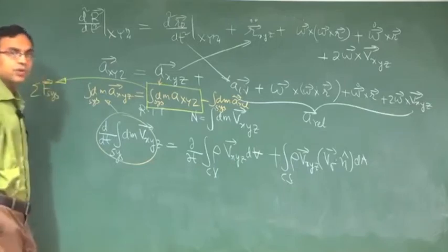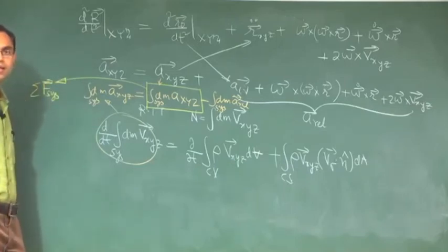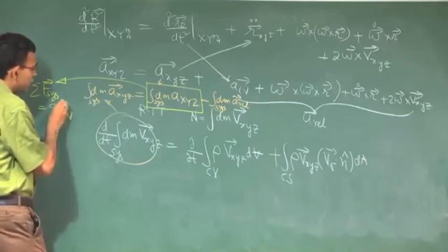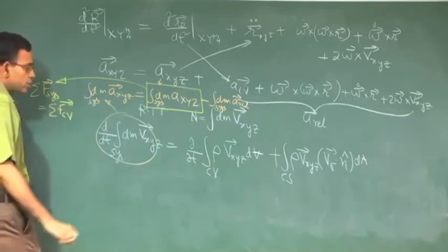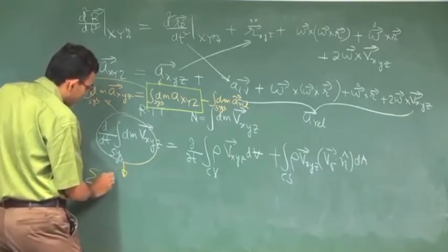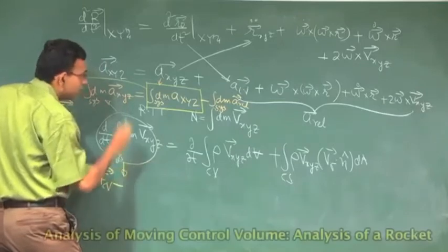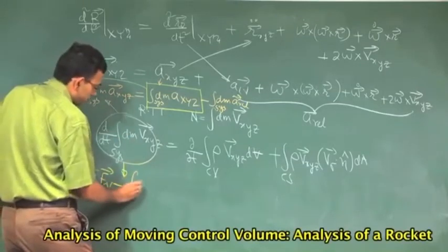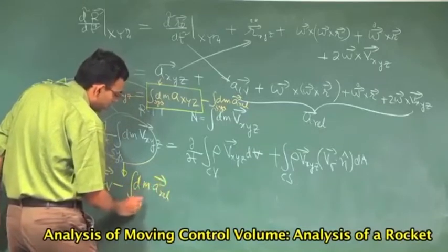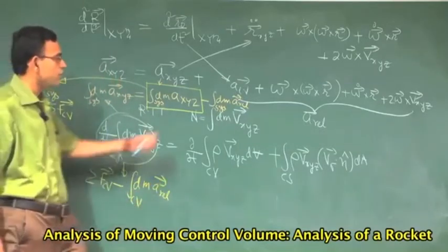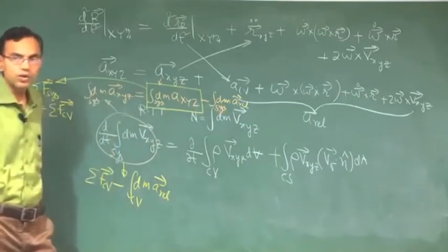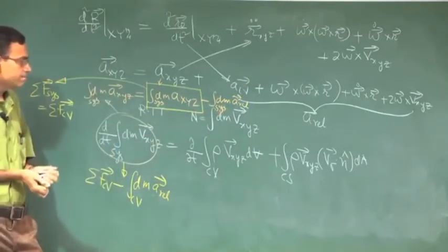As the Reynolds transport theorem was derived in the limit as delta t tends to 0, so this will be resultant force on the control volume. So this term will be resultant force on the control volume minus this, which you can also evaluate on the control volume by noting that in the limit as delta t tends to 0, system and control volume are converging.